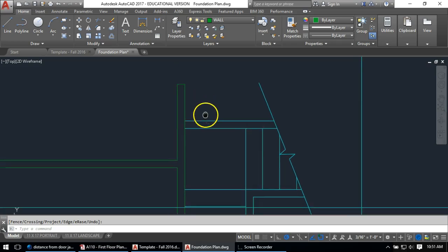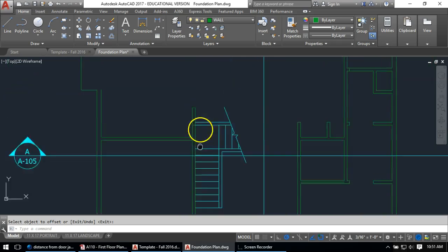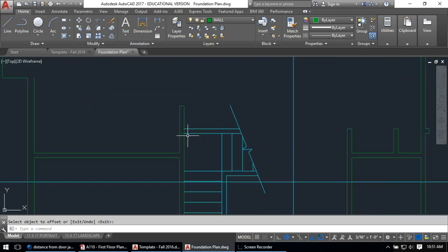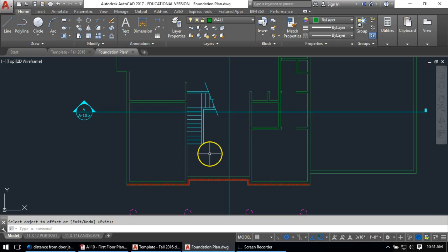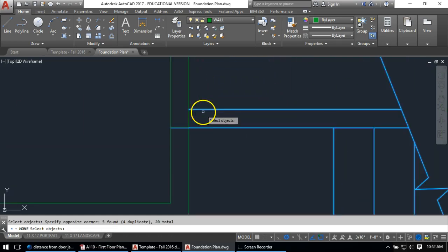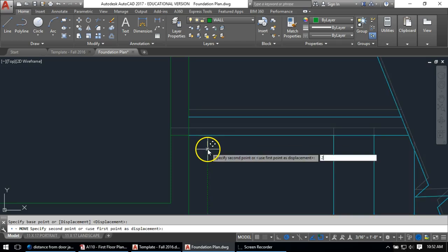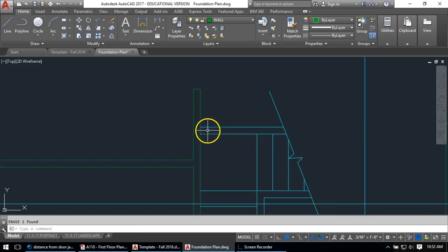In theory, again, it depends on how accurate the stairs were in the basement, I should be able to offset 2 foot 2.25 and get the center point of this railing, and we can see that is not the case there, and that these stairs would be moving down. So I'm going to move them down in my plan, and if I'm moving them down in plan, move it 2.25, they should be located correctly to get that dimension.